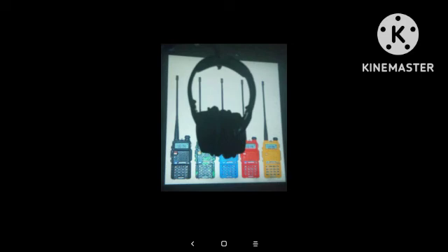Number 15. Before checking a fault in a mains-operated power supply unit, it would be safest to first turn off power and remove the power plug. Number 16. What is the safest method to remove an unconscious person from contact with a high voltage source? Turn off the high voltage switch before removing the person from contact with the source. Number 17. What should you do if you discover someone who is being burned by high voltage? Turn off the power, call for emergency help, and give CPR if needed.